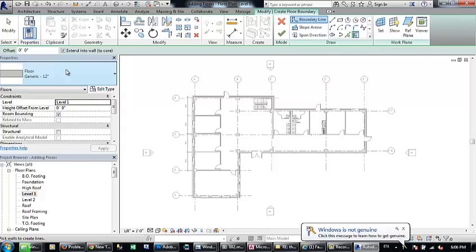It's not mandatory for the slab to extend to this level, because this level is not carrying load. It's mandatory for the slab to extend to the core face. Again, in our example, the generic 12-inch floor family, the wall thickness is the same as the core thickness. There is no core even on this one. So right now I will use these tools in order to draw the slabs.